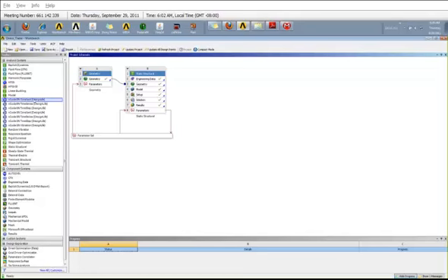In this case, EN stands for strain life and SN stands for stress life. Basically, it has 3 of EN, 3 of SN: constant amplitude, where your cyclic loading is of constant amplitude; time series, where you have a time history, whether the time history is coming from your experimental data or your test tracks; and also you can do a time step. This repeats the same thing for your stress life also. In addition to that, you also have SN vibration, which you can use for your nCode vibration fatigue, random vibration fatigue.